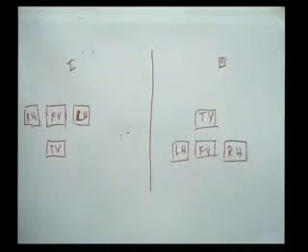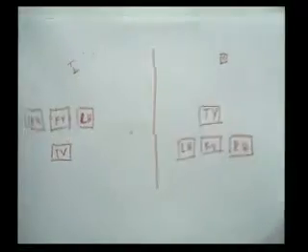So the solution varies depending on whether I am asked for the left hand side or right hand side view. When I am having a left hand side view in first angle, then it is drawn on the right hand side. That's what will happen in this particular question. I am told to draw the left hand side view, so wherever I draw my top or front view, beside that, on the right hand side, I will draw my left hand side view.